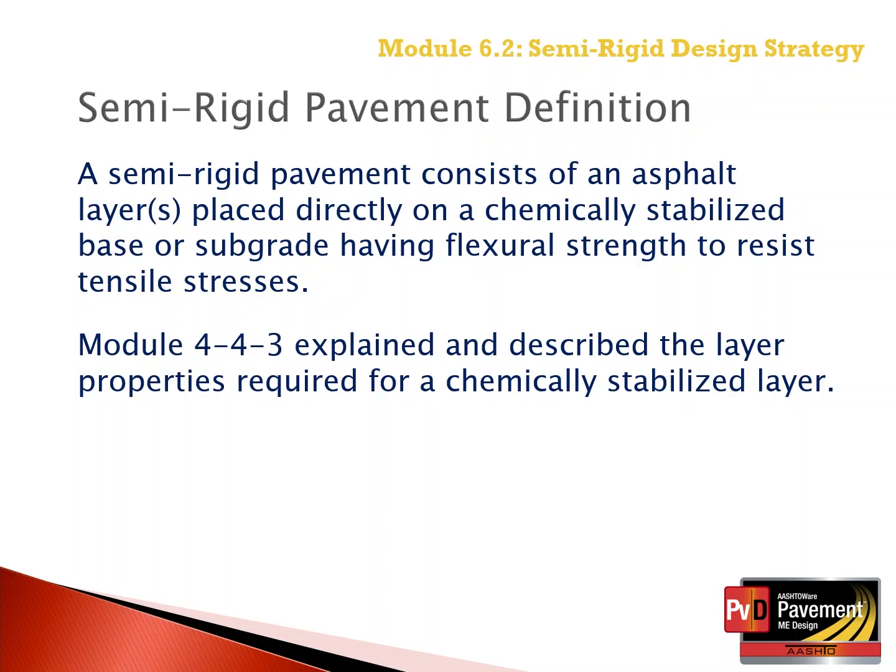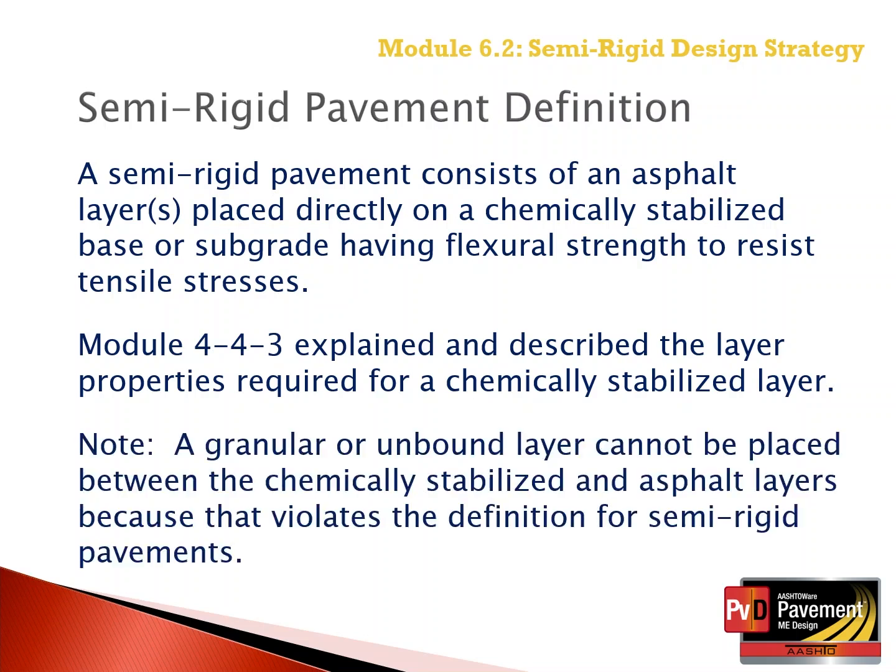Under Module 4-4-3, we explained and described the layer properties that are required for a chemically stabilized layer in accordance with using the Pavement ME design software. A specific note to make: a granular or unbound layer cannot be placed between the chemically stabilized layer and asphalt layers because that would violate the specific definition for semi-rigid pavements.